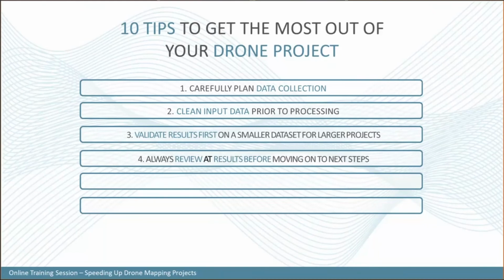Specifically the AT, I would say you should review most of the steps, basically the AT and probably the DEM. But the AT is where all the accuracy is getting computed. So you want to make sure that your quality report meets the accuracy you need to have for your project, and your block is nicely tied together. You have sufficient GCPs, and so on.